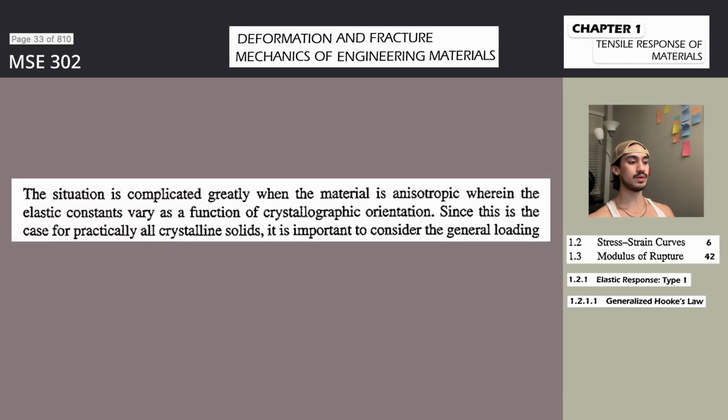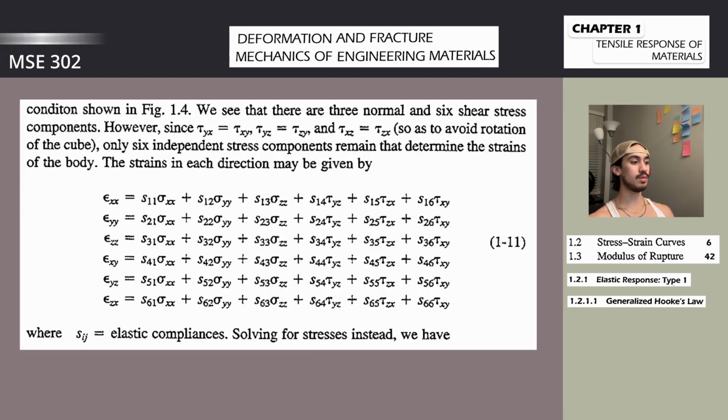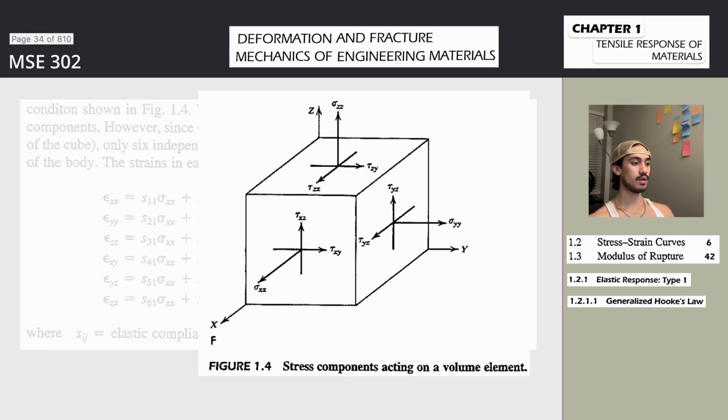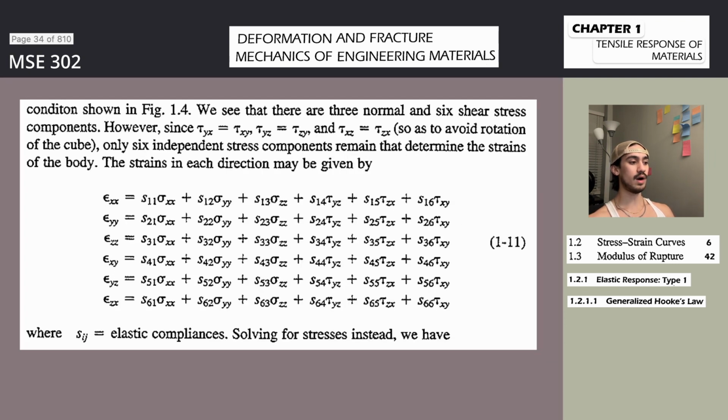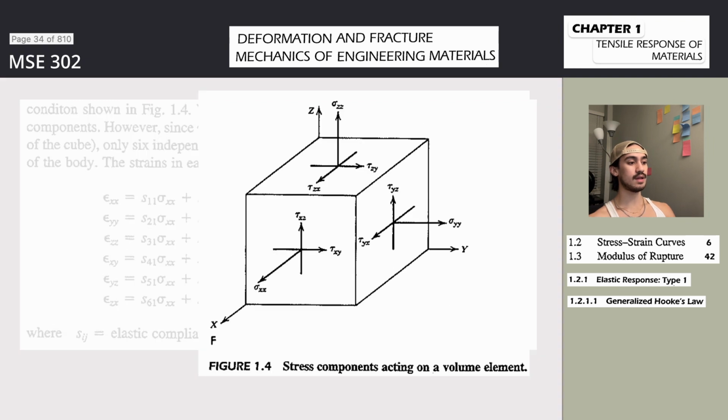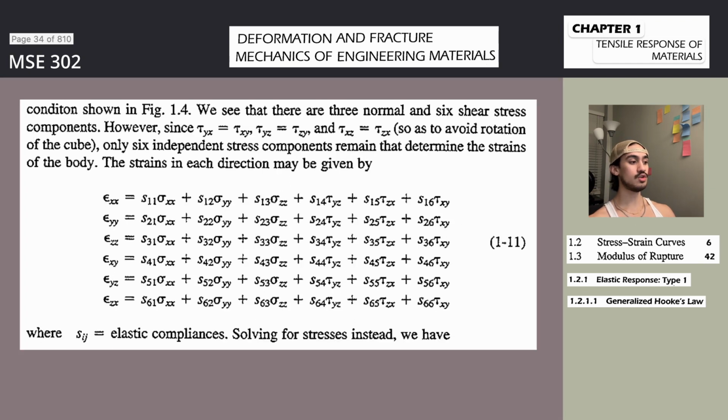Such data may be derived by plotting true stress and associated true strain values on log-log paper. If Equation 1-20 were absolutely correct, a straight line would result with a slope equal to n. However, this is found not always to be the case, and reflects the fact that this relationship is only an empirical approximation. When a nonlinear log-log plot does result from a given material, the strain hardening coefficient is often defined at a particular strain value. In general, n increases with decreasing strength level and with decreasing mobility of certain dislocations in the crystalline lattice. More will be said about this material property in Chapter 3.